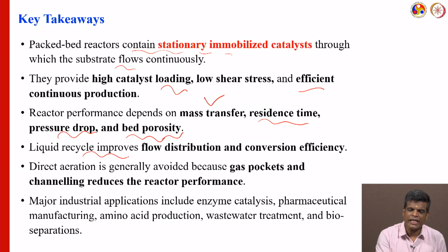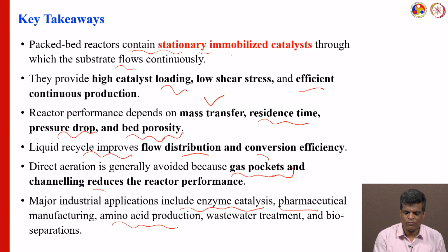So, definitely liquid recycle improves the flow distribution and the conversion efficiency also. Direct aeration is generally avoided because, as we already discussed, channeling occurs and gas pockets form, and these reduce the reactor performance. So, what are the major industrial applications here? It is definitely used for enzyme catalysis and the pharmaceutical manufacturing industry. Sometimes for amino acid production, wastewater treatment, and bioseparation. These are the applications.